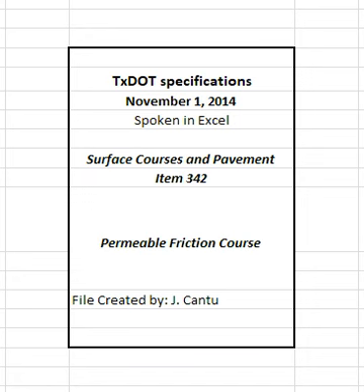2.5.4 Warm mix asphalt, WMA. Warm mix asphalt, WMA, is defined as HMA that is produced within a target temperature discharge range of 215 degrees Fahrenheit and 275 degrees Fahrenheit using approved WMA additives or processes from the department's MPL. WMA is allowed for use on all projects and is required when shown on the plans.